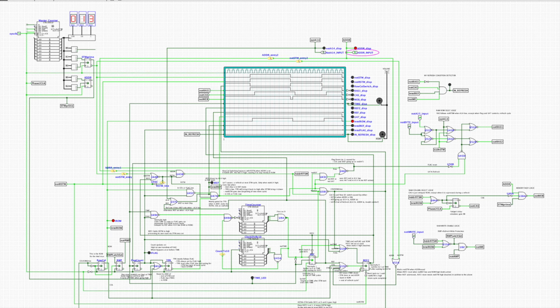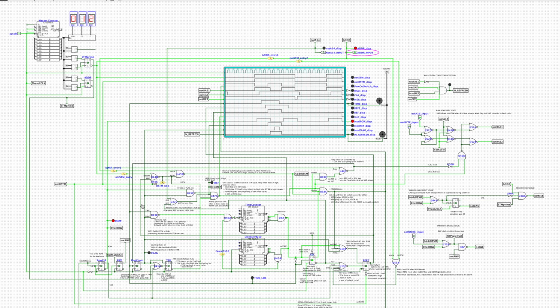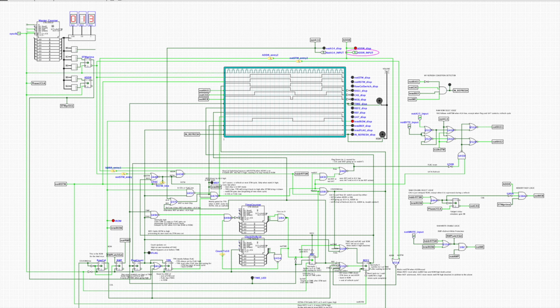And this is all very complicated. These 2 gates control when the refresh counter is exposed, and it's also completely loopy. This one is armed by the time signal, but it has to wait for this one to come up, which waits for the STM, and then when it comes off, it has to wait for this one, which comes back here and comes back here. So no wonder we couldn't figure out what was coming out. Once again, this whole thing didn't work until I put the last wire.